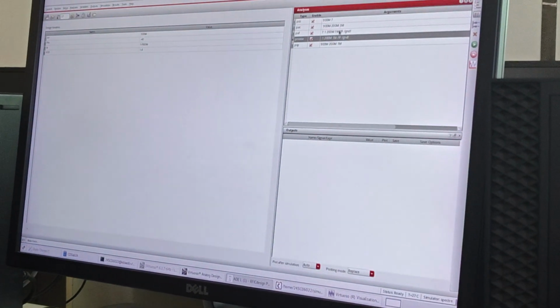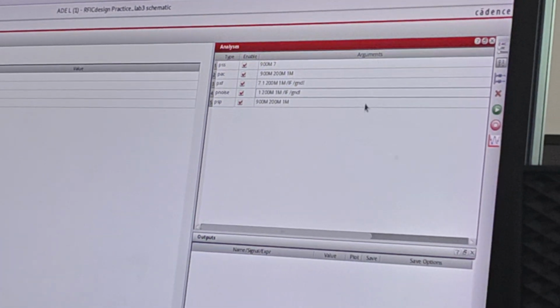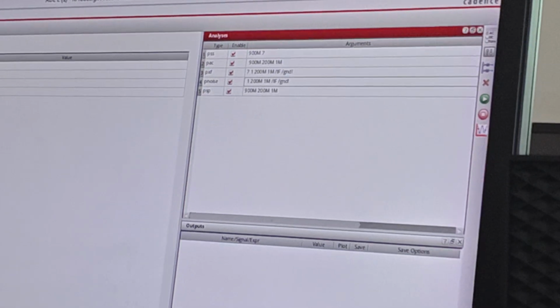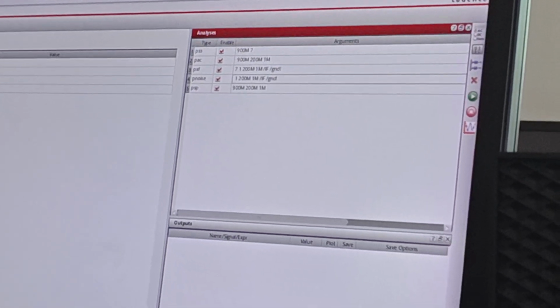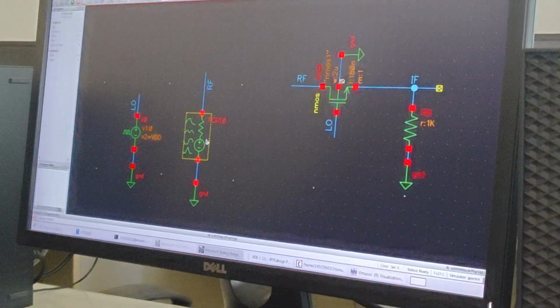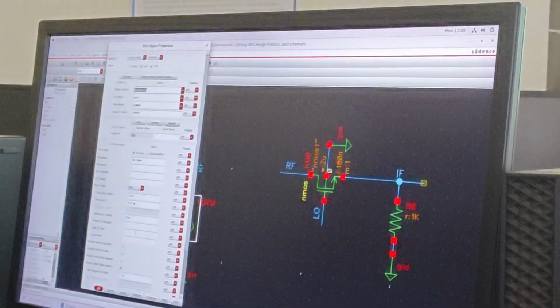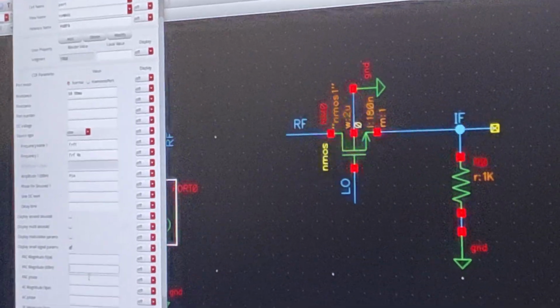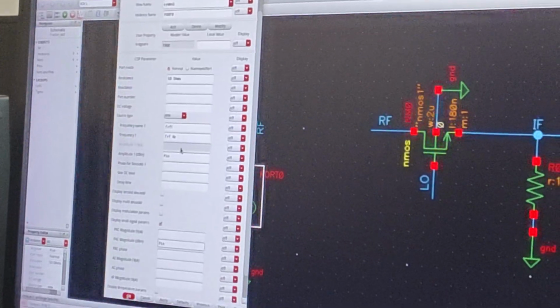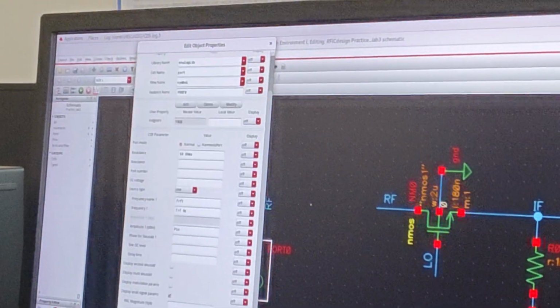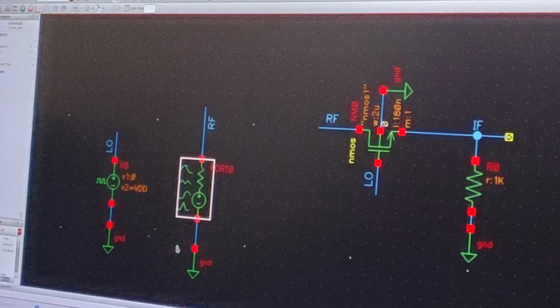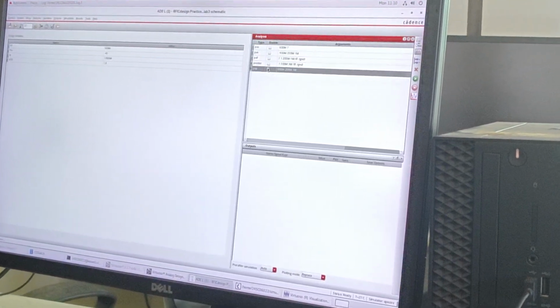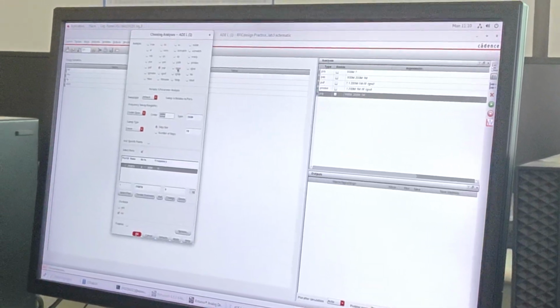Okay, so these are the conversion gain, noise figure, and S parameter simulations. Another one we wanted to see is the linearity simulation, IIP3. For that we'll do QPSS and QPSC. Before doing that, we'll make certain changes. Instead of giving a constant 1 volt, for this PSC magnitude you give a variable, let's say the same as in the LNA. For both, I give the variable Pin. That Pin is anyway here, -40 something. I'll disable all this. In the analysis, select the QPSS.